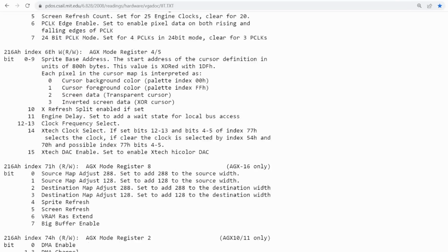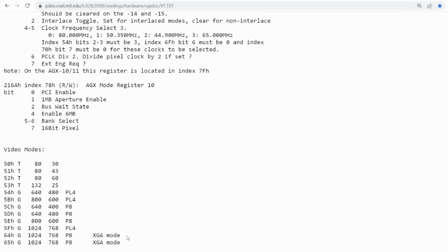And in any case, we're really interested in getting the coprocessor going. Well, it may not look like much, but I have the coprocessor working. This line was drawn with a drawing function of the coprocessor. And I had a little bit of anxiety about this because in order to draw anything at all, you have to set up a destination pixel map. And the upper left corner of that is given as a 32-bit address. But how do I do that on a 16-bit system like DOS?